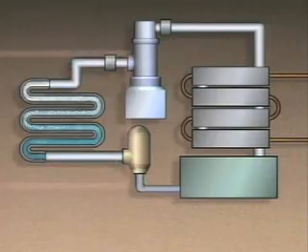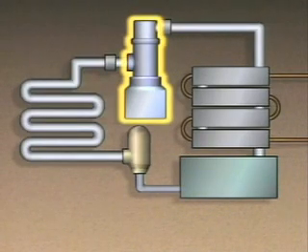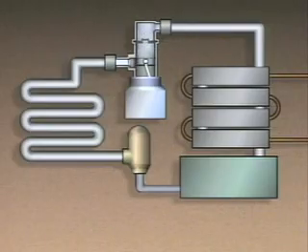evaporator's surroundings. To move the refrigerant through the cycle, energy must be added to it. For many refrigeration cycles, a compressor is used to add energy to the refrigerant so that it can move through the cycle. The compressor receives the refrigerant vapor from the evaporator. Energy is added by squeezing or compressing the vapor into a relatively small space. This increases the vapor's pressure and temperature.